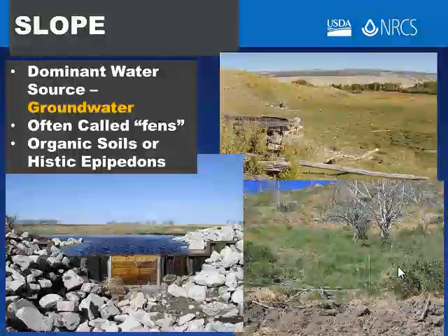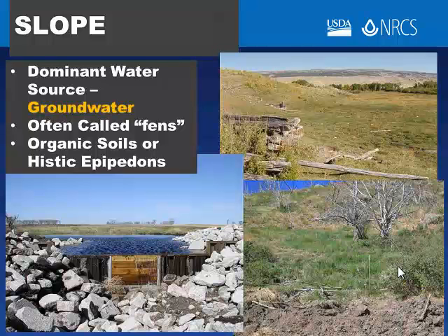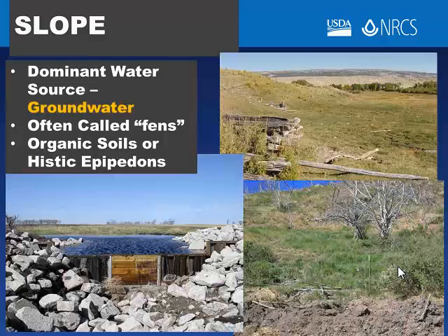Moving up the watershed, out of Riverine, we're going to go to slope wetlands. The dominant water source of slope wetlands is groundwater, and this is where water actually moves into the wetland with a vertical upward vector. There's actually hydraulic head in a flow net starting in the adjacent uplands that collect precipitation and then discharge into these wetlands. And they're typically found in low-order reaches in a watershed network, and in some parts of the country they're quite ubiquitous, and in other parts of the country they're limited to small seeps and springs and headwaters.